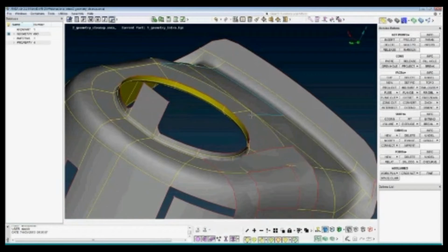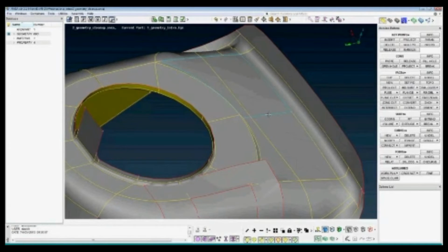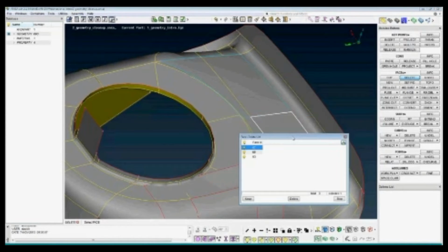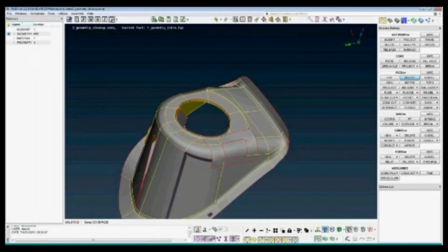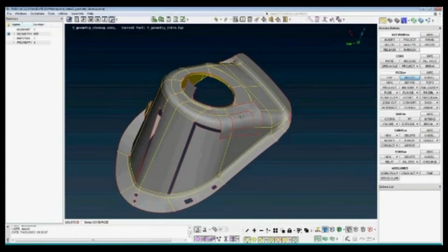First, we can delete the face. Face, delete, click on the edge and get 3 faces connecting to this edge. Probably this face is wrong. So I delete it and stop. Problem is fixed. Again, I activate the crosshatch for more simple selecting faces.